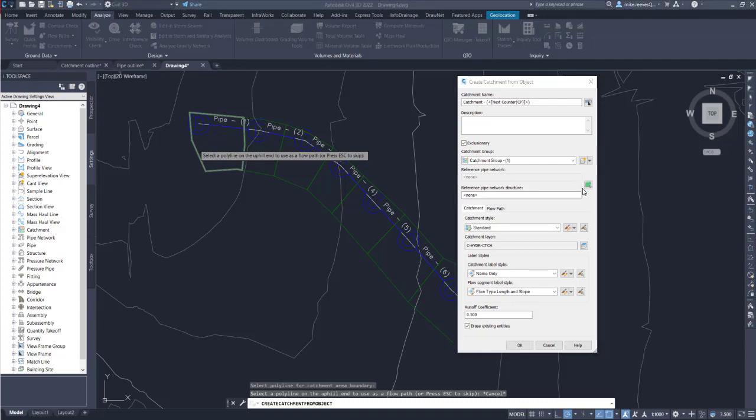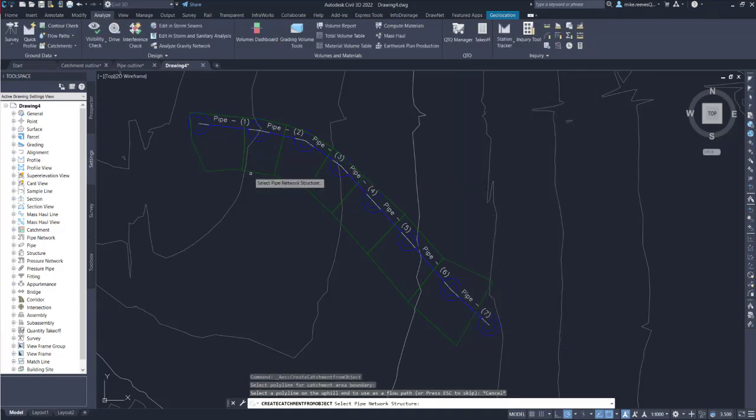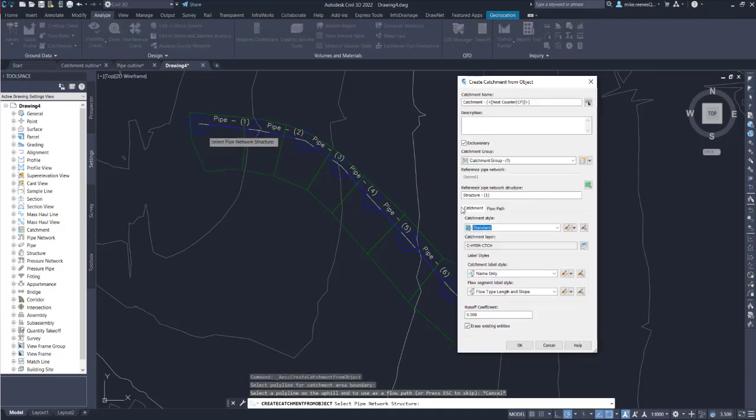and in this dialog the main thing that I want to do is to associate the subcatchment with the manhole that it's going to drain to. Now InfoDrainage has some great automatic utilities that do that for you, so you could just export them like this and then allow InfoDrainage to make the connection between the subcatchment and the manhole. But if you want to specify and define which manhole it drains to, you can do it at this point. So all we need to do for that is to click on this box and then pick the manhole that we want to drain to. I think that's it. Is there anything more to it?